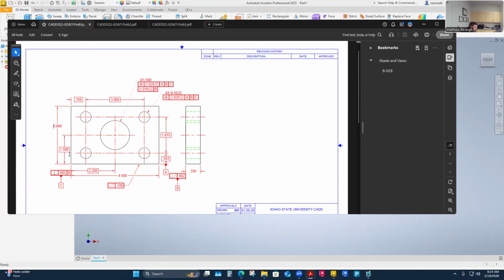So anyway, I just want to keep this one a little more basic than it is. But these are basic dimensions. Not all of them are basic, only the ones that are really driving a control. But I would argue on that. I'd have to look through these dimensions and say, okay, if it's a basic dimension, it should be coming from a datum, and it should be used to locate a feature of size. And so I'd have to look through here and say, are all the ones that are basic dimensions? Yeah, I think so. I think the basic dimensions have been identified correctly here.